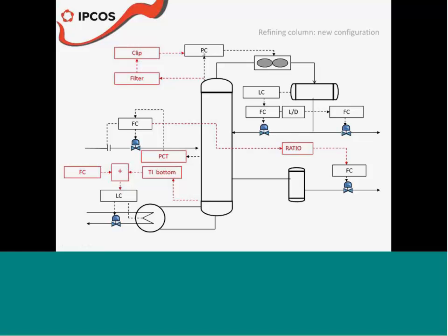This at the end, what does is it keeps the pressure floating but not changing drastically like it used to do before. Before, because the set point was constant, the fin fan coolers were pretty much just open. The fins were opening and closing all the time, and no real regulation was done. Here, the pressure was, let's say, changing with the atmospheric conditions, but in a much more smooth way, which reduced disturbances to the rest of the operation.